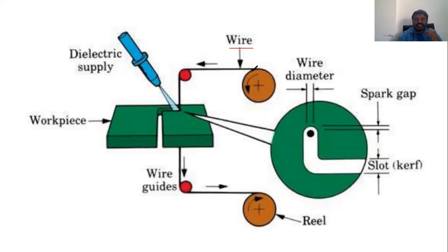See, it is connected with the roller. We are passing this wire against the workpiece. The wire is connected to the cathode, and the workpiece to the anode. The basic point is that we are going for a thin wire, which should be thermally conductive. Due to that, ionizing can take place. That is the reason we go for a thermally conductive wire material: brass, copper, or tungsten.